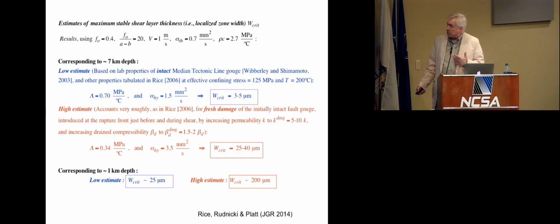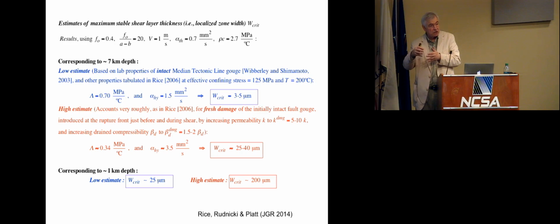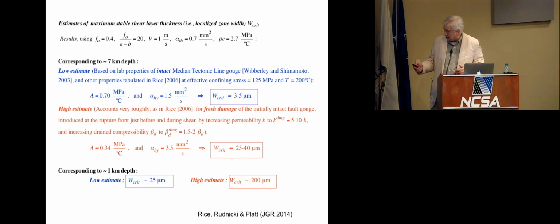Now, one of the big problems we have in saying, how do we think about this in a real earthquake, is that the earthquake rupture is basically a mode 2 crack propagation. As the rupture comes along and approaches a given point on the fault, you have massive stress changes associated with the rupture tip. That certainly has to deform and crack up or otherwise damage material. And we don't have very stringent guidelines for guessing how much that alters permeability and compressibility, the two things that would be most susceptible in this scenario to damage.